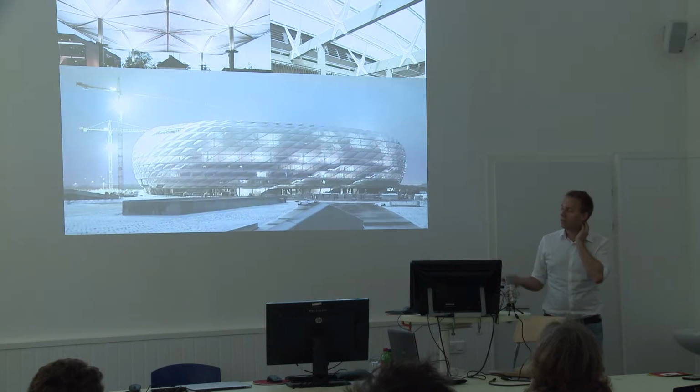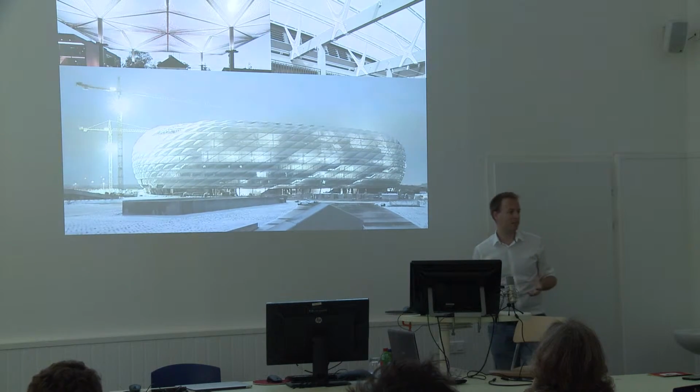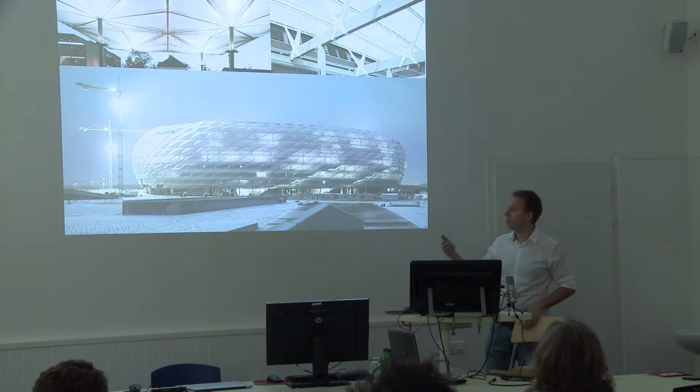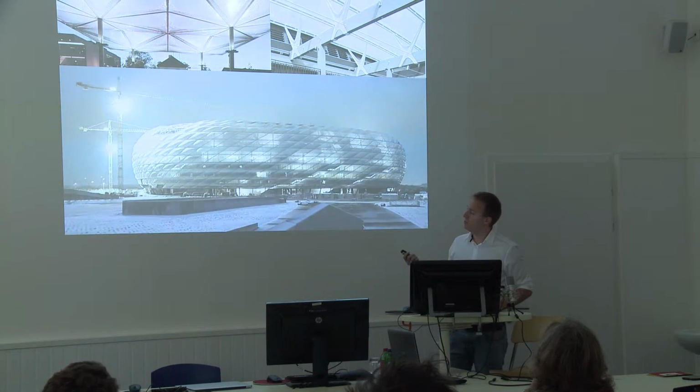They have some very strong characteristics. For example, they have an almost negligible dead load, which is very unique compared to the span that they can cover. They're very, very light constructions. The other main point is that there is only tension in the surface.